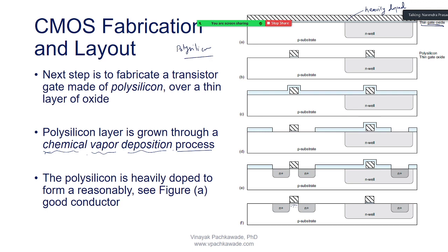And so let's say these two are in. And this is the oxide. You see, this is the thin layer. What you see in the first diagram A, you have the final diagram F. So this is the SiO2 or silicon nitride, just the oxide. This is the polygate, and the channel is just a semiconductor. Channel is below the oxide, obviously, below the gate oxide. Yeah.